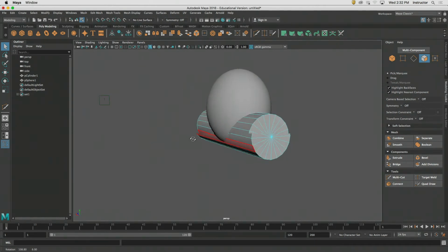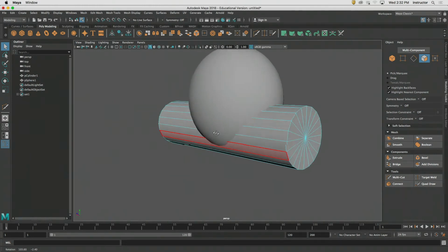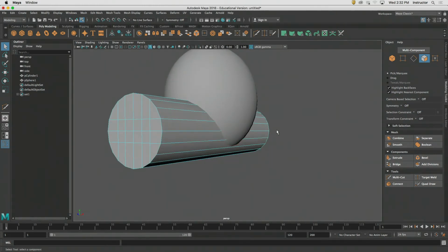So one thing that we can do that's kind of fun, and this is a good time to explore it, is looking at soft selections. Okay? Because what I want to have here is a shape that's more cylindrical on the top, but kind of flat on the bottom. Nothing in our world is made up of 90-degree lines unless you're a building. Okay? If you're working in the organic space, everything is a cylinder. There are no straight lines in nature. Okay? So we should try to avoid perfect 90-degree edges and very quick transitions between planes.